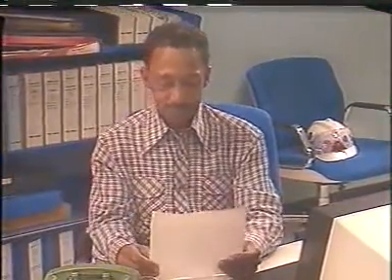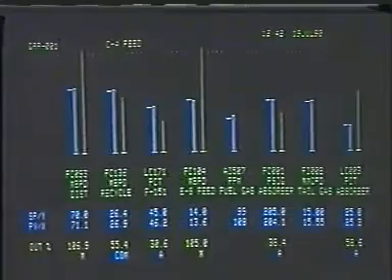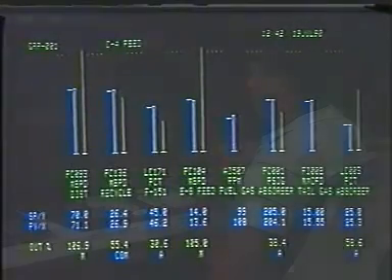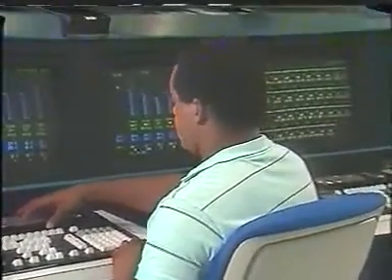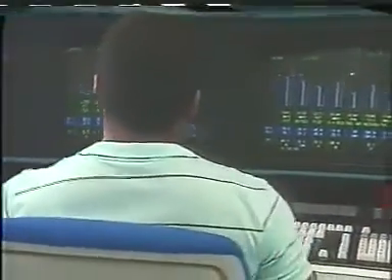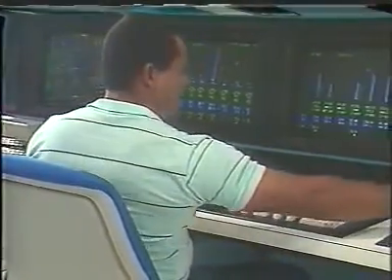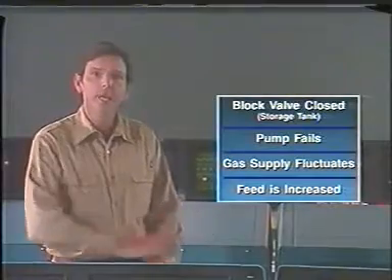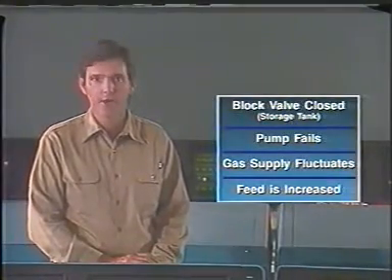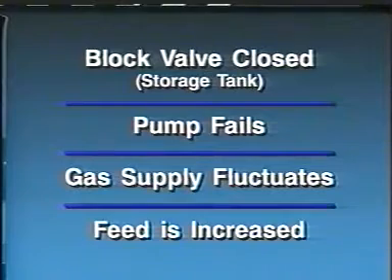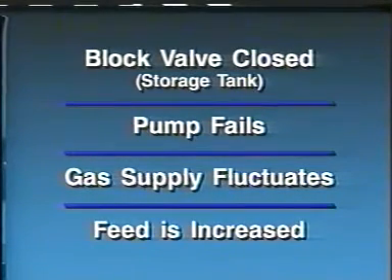In another problem, the foreman for this crude oil distillation unit gets instructions to raise production by 50 barrels per hour during his shift. As the unit operator increases feed, he must also take some other things into consideration. For example, if he increases feed too fast without also increasing the reboiler fuel supply some, a drop in process bottom temperature results. This list names the examples of process upsets we just described. In two of the examples, the process cannot be returned to set point by automatic controls. Decide which two examples they are.